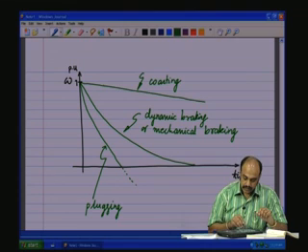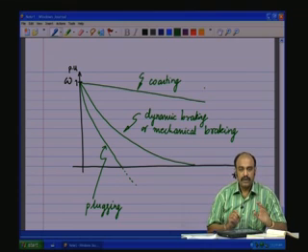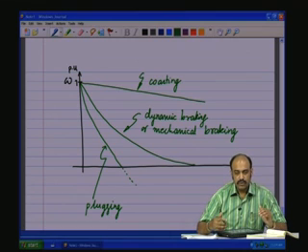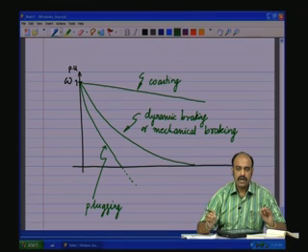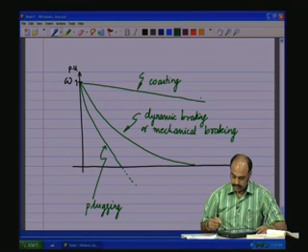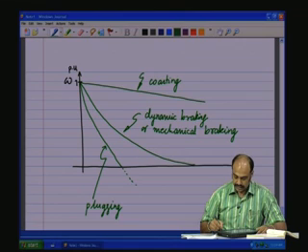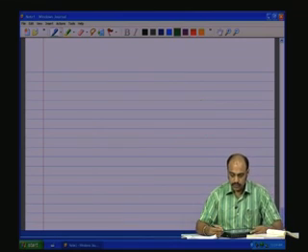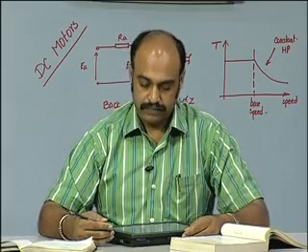And in the case of coasting, it is slowest. There is no control on that, except that it will go to 0 due to the energy which is lost in the bearing frictions, windage and things like that. So, that can take quite a long time if the load inertia is very high. So, that is about the braking.